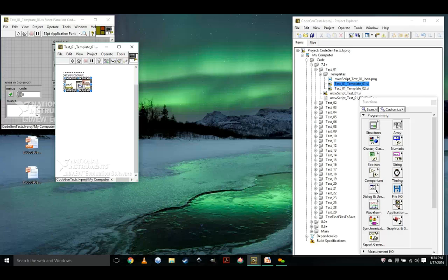So, if I understand this right, somewhere in the Codegen engine, it says, oh, I have a template. I'm going to go with this block diagram. It's going to look for a sequence structure called MXW Framer, and then grabbing everything inside of it is actually like a single scripting call. Well, it's actually easier than that. You basically get the reference to MXW Framer, and you do a move. Move is the fastest thing to do. There's no copy, no paste, no nothing.